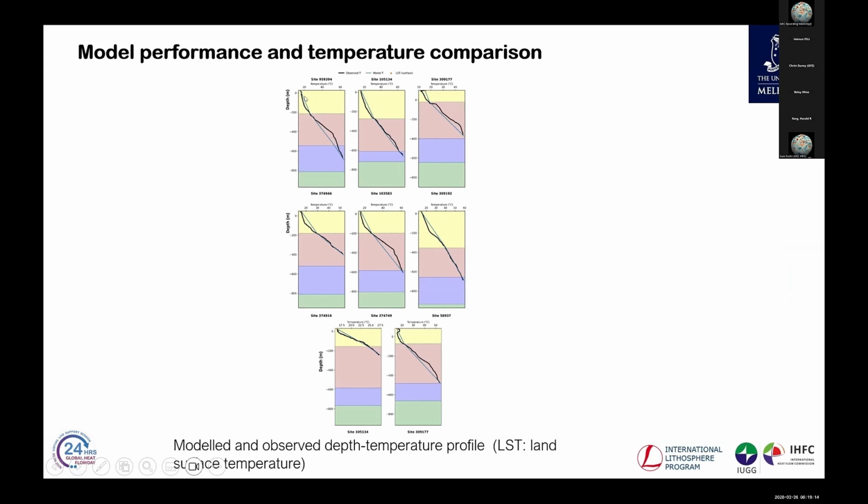Of course, if you look against stratigraphy, the blue line is usually straight. It does not clearly change with the stratigraphic boundaries, but this is because we have assigned fixed boundary conditions at the top and the bottom. This enforces the model temperature to have linear geothermal gradients.